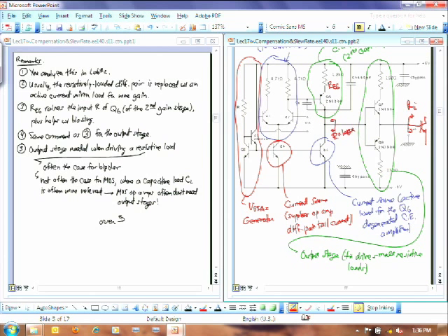And so that's what this is all for. That's a large resistance, but because I'm using this resistor and that, the resistance looking in is even larger. So it's even larger than that resistance. And so now I'm driving that driver stage without losing the gain from this second stage, because the driver stage resistance is not loading this stage.